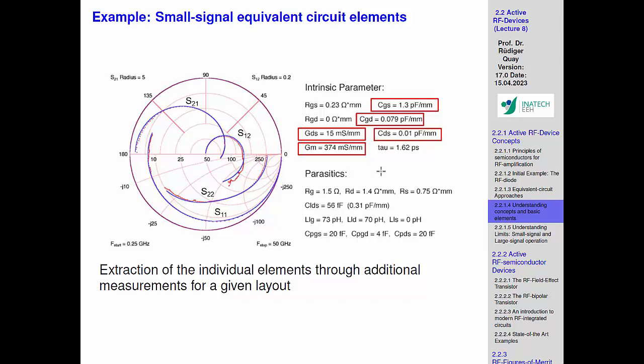So this is why there's always this millimeter appearing, because it's clear that a larger FET, which has the same gate length, channel length, has a different capacitance than a smaller one. In order to take that out, we always relate most of the things just to this length. It's the third dimension, which we are not seeing.